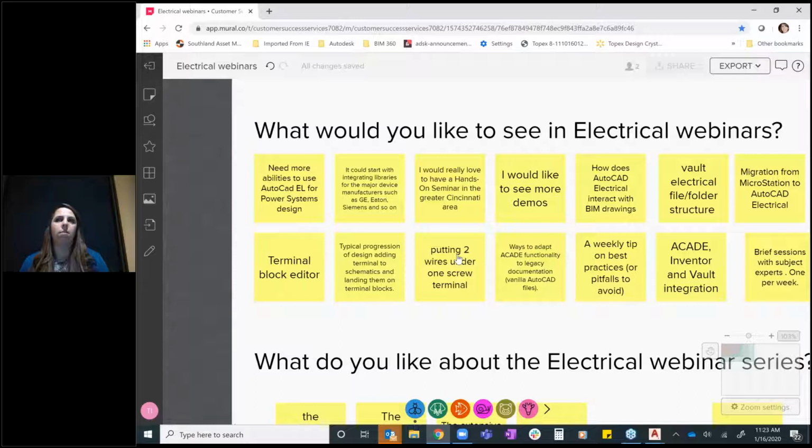So there's a key to AutoCAD Electrical that often happens with people, where if you don't choose what you actually want installed, you only get a few manufacturers. So it's really, really important that you actually go in and choose that you want all manufacturers installed if you think you're going to use those, or choose your specific manufacturers.